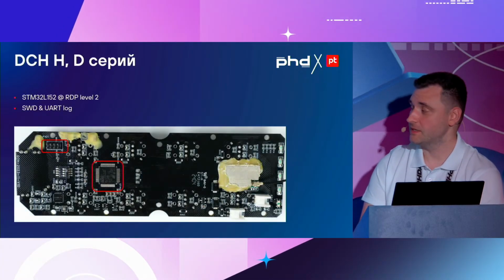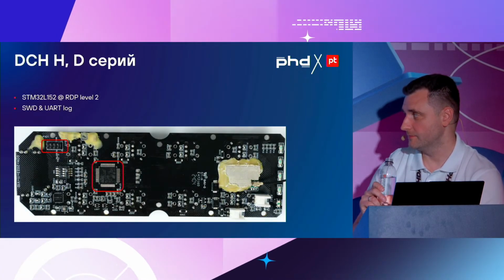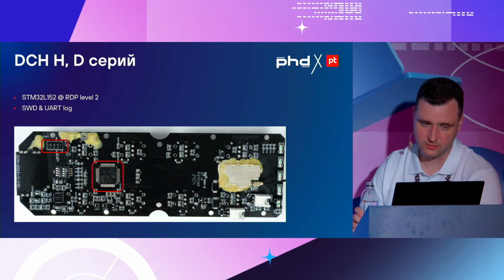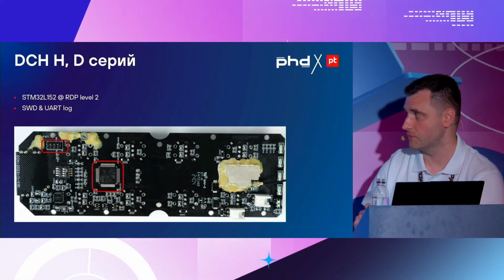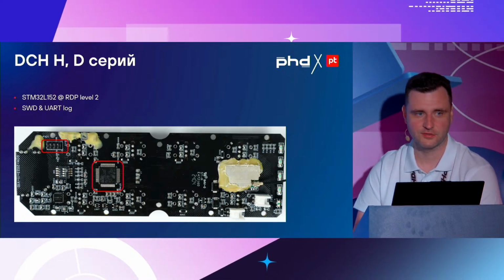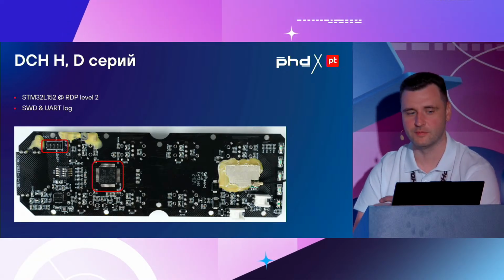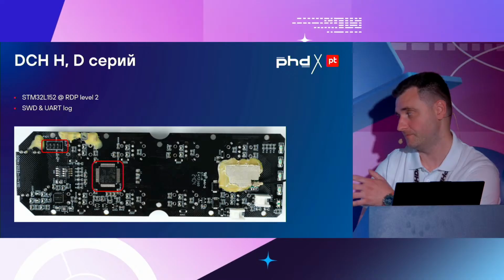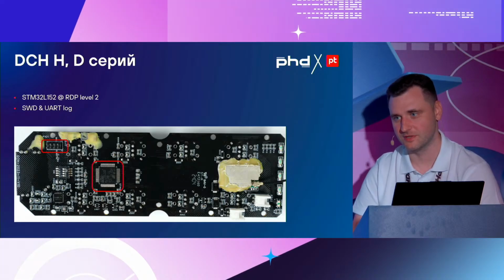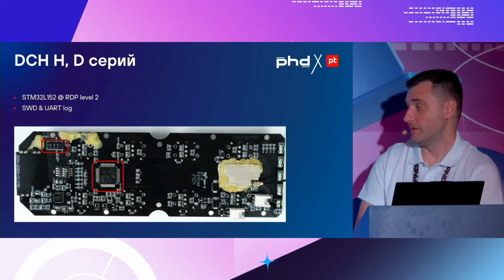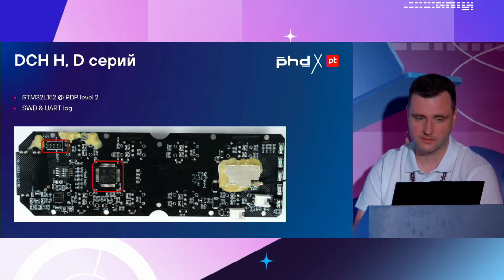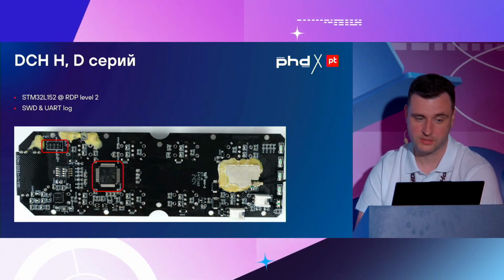Let us do reprogramming. So this is the STM level 2, but apart from that, there is UART. UART shows the log of what is being pushed, and in essence, we didn't even have to sniff SPI. In order to restore the protocol, it would be enough to look at the UART. But the process was streamlined, so first we sniffed the SPI and looked at everything else, although probably the right decision would have been to look at the UART. UART has a log, but you just have to decode it.